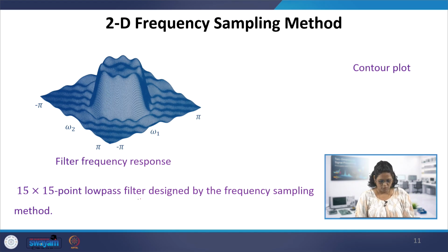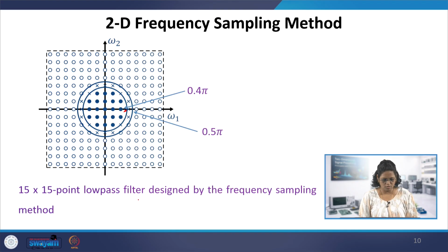So we need to add the low pass filters for k equal to this up to here, you can have 1, 2, 3 if it is, and then these resonators should be avoided, and only these resonators should be there in the structure. So we need to fix k, what is the bin index corresponding to the fundamental, second and third harmonic. Accordingly this omega can be translated into that. So we can have these samples, these resonators to be added in the summation, and the resonators of the rest of them should be removed from that.